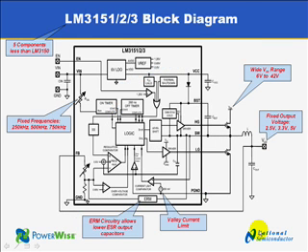This slide shows the block diagram of the fixed frequency and fixed output voltage device options. It saves 5 external components. The resistor to program the peak current is saved, as the peak current is set by the RDS on of the low side MOSFET.